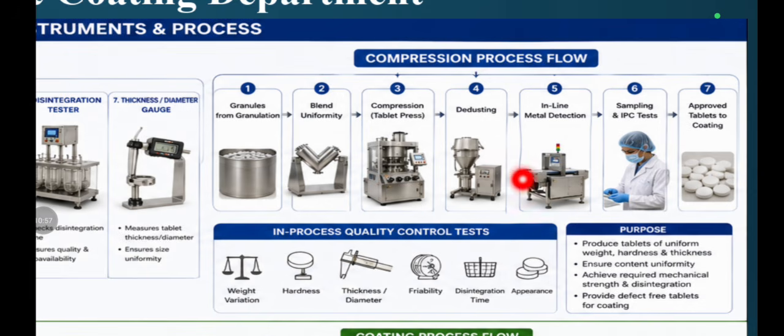After that, it goes toward the IPC test, the in-process check test, with sampling. After completion of the in-process tests, like friability, hardness, disintegration and thickness, once it is approved, the tablets are approved for coating.